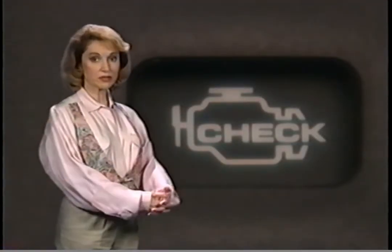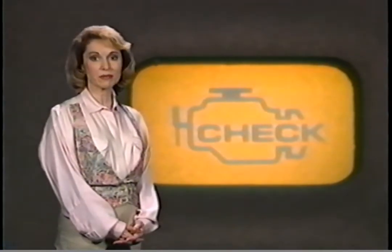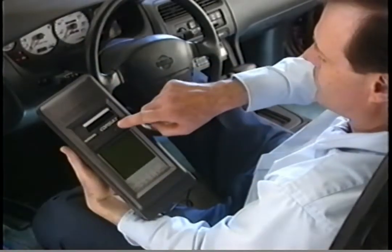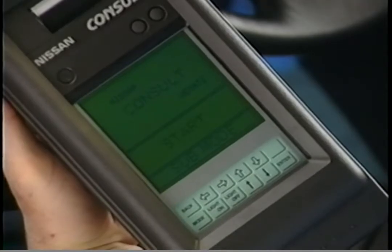If a Nissan vehicle with the OBD-II system comes into your dealership with an illuminated MIL, you diagnose the problem much the same way as for any other vehicle. To isolate the malfunction, use Consult. Make certain the most current software is loaded into the Consult memory.